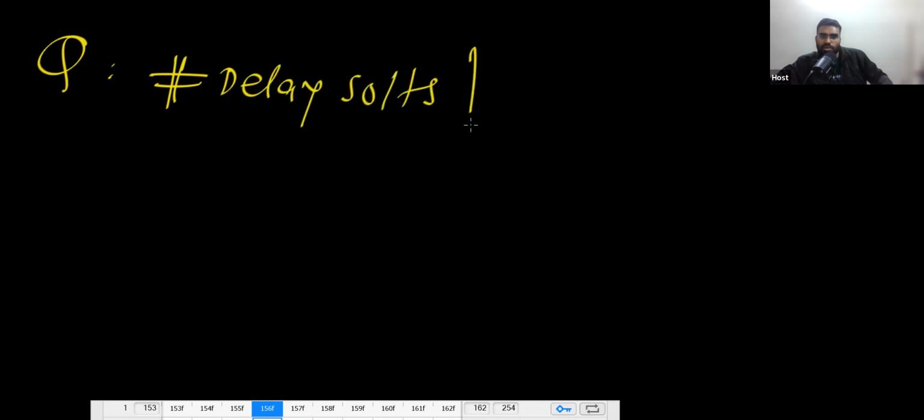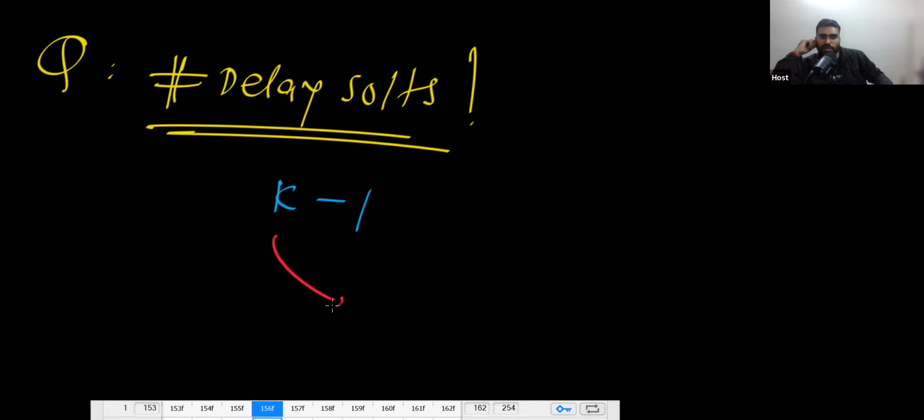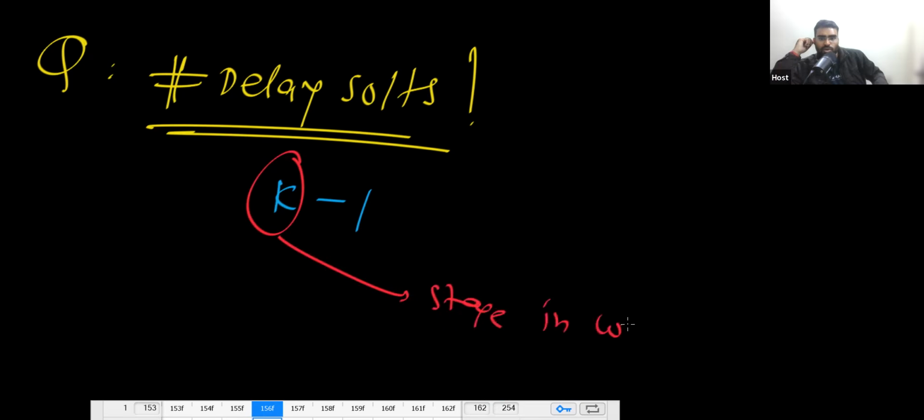How many delay slots are there? What is the number of delay slots? That is k minus 1, where k is the stage in which the branch is resolved. What is this k? This k is the stage in which the branch is resolved.